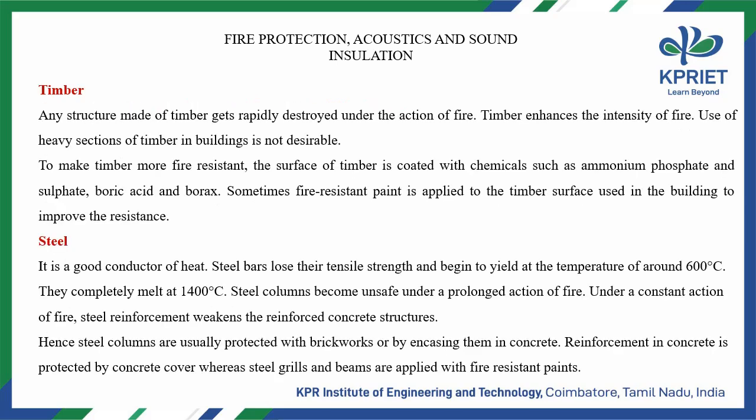Timber. Any structure made of timber gets rapidly destroyed under the action of fire. Timber enhances the intensity of fire. Use of heavy sections of timber in buildings is not desirable. To make timber more fire resistant, the surface of timber is coated with chemicals such as ammonium phosphate and sulfate, boric acid, and borax. Sometimes fire-resistant paint is applied to the timber surface used in the building to improve the resistance.